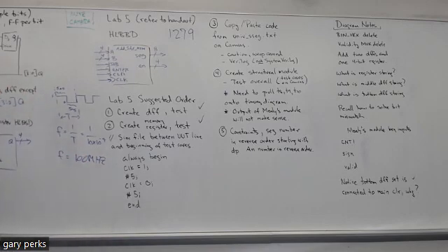And the reason why we use this 10 nanosecond period, 100 megahertz frequency for the simulation is because that's what the Basys 3 board runs at. Okay, it runs at 100 megahertz. So when we separate the test cases by 10 nanoseconds, we're essentially doing a test case for every clock pulse. Right, because you get a clock pulse every 10 nanoseconds, or it's running at 100 megahertz rate on the Basys board. Okay, so that's the reason for those numbers, in case you were wondering.